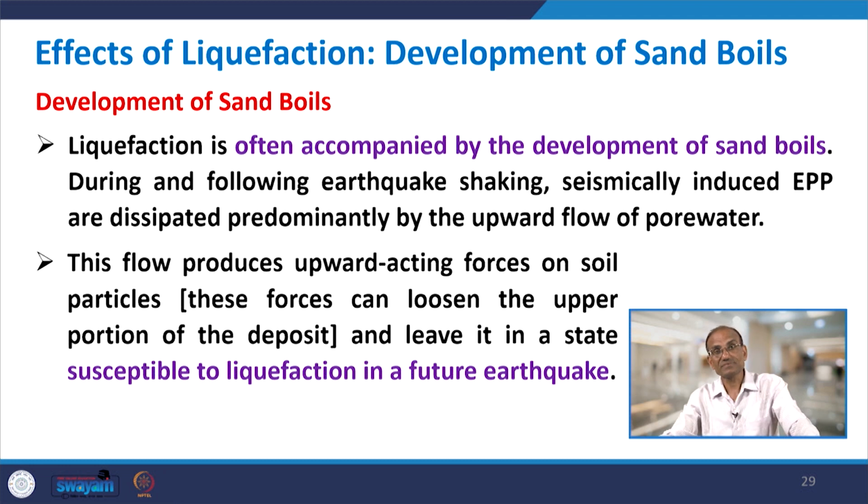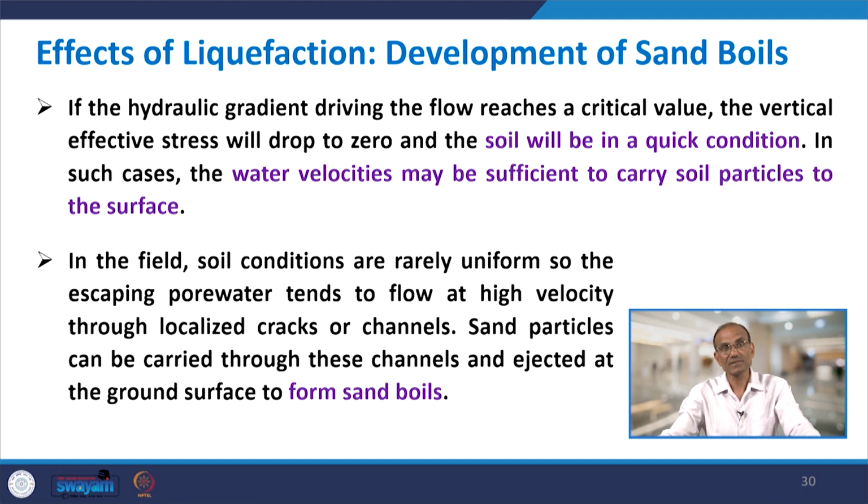As a result, this is called the development of sand boils. This flow produces upward acting forces on soil particles, and those forces can loosen the upper portion of the deposit and leave it in a state susceptible to liquefaction in future earthquakes. So, if it is subjected to another earthquake in the future, it will be susceptible.